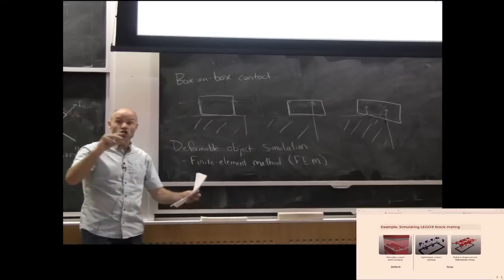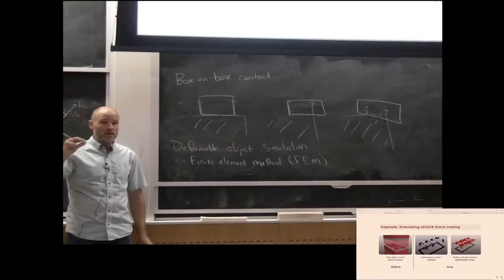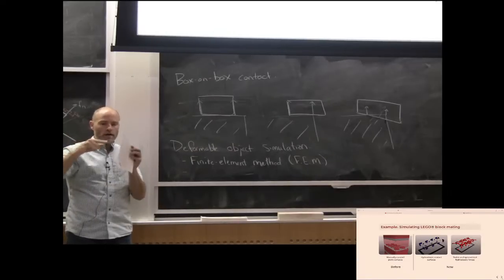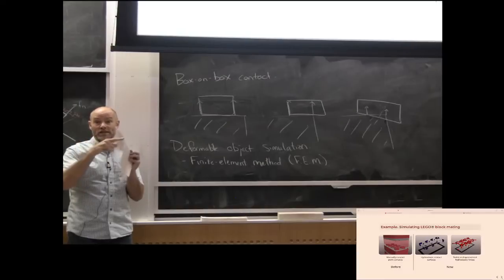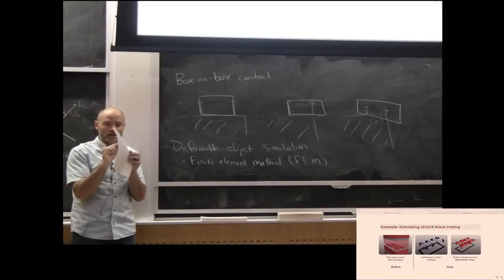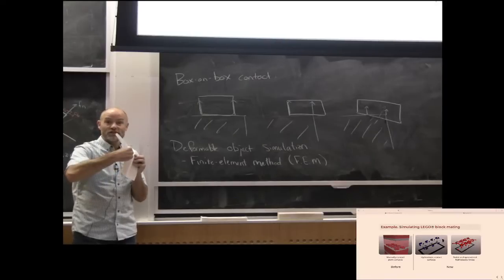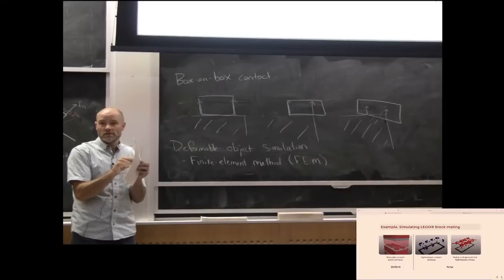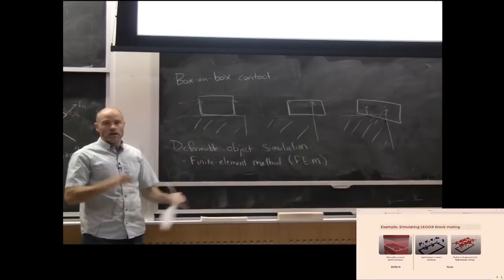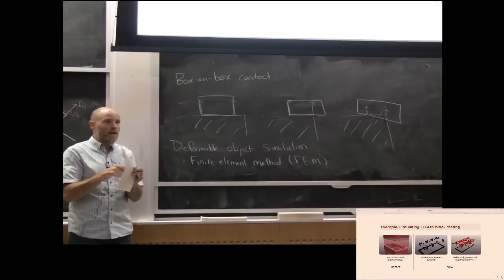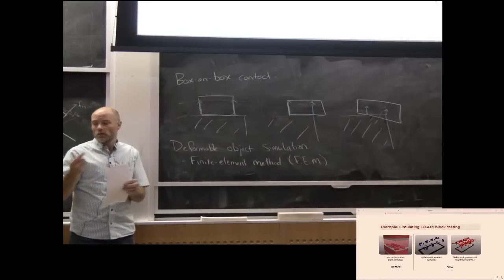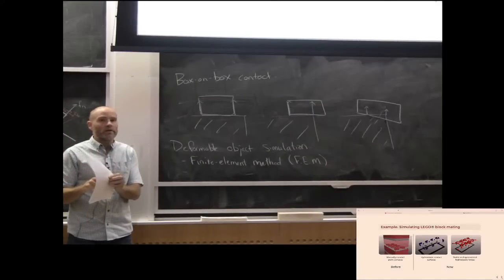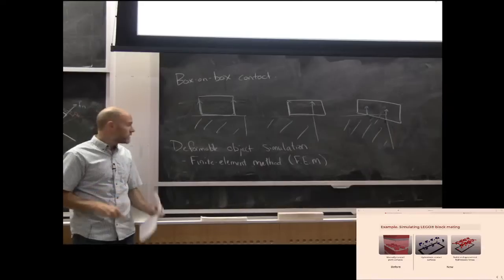But let's say I wanted a plush toy or something large and soft. When you get to cloth simulation, that's an extra level of complexity because you have to worry a lot about thin objects. You can have piercing phenomena. If you take slightly too big of a time step, part of your object is on the other side of the object. So you just have to deal with these breakthrough events. But you can do that, again, with a finite element method, for instance, with extra work. But I don't claim Drake can support cloth yet. That'll be future work.